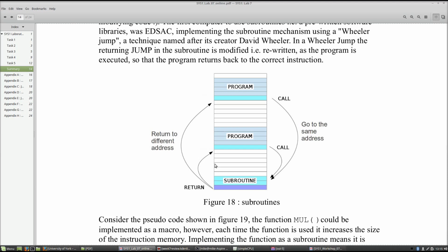Again, just really to emphasize those ideas about what an instruction is and how it is represented within our memory. Obviously, again, we're going to replace this technique that uses self-modifying code in our final processor, the simple CPU version 1D, and we're going to implement a call and return stack, as you would see in a typical processor. But again, as we will see, adding more addressing modes and adding more instructions do come with a hardware cost, and we'll see that in later lectures.